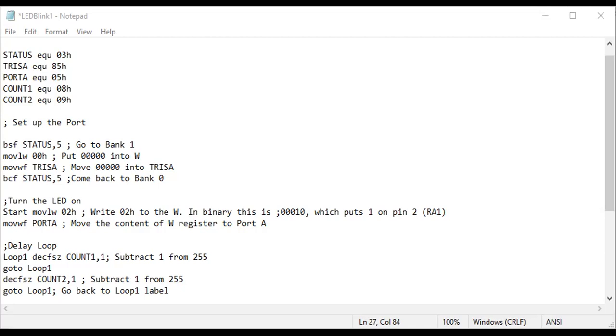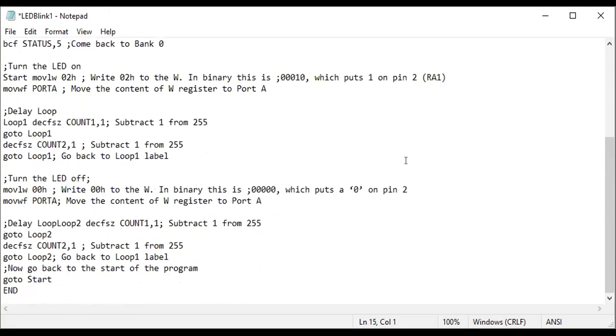After putting that in there, we just need to run the program. Proteus will read our .hex file and then execute it. The .hex file is the form that the machine, or processor, can understand. So that's what we have done with MPLAB IDE.